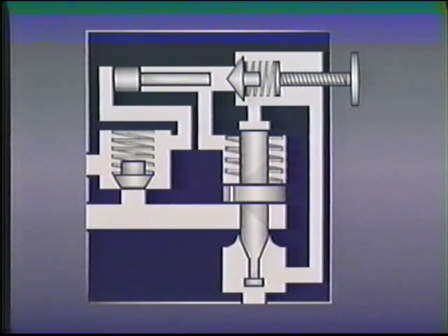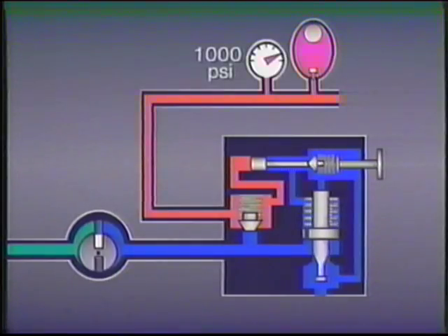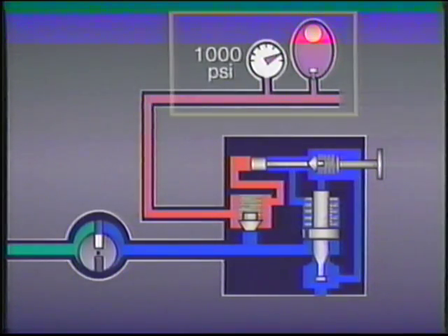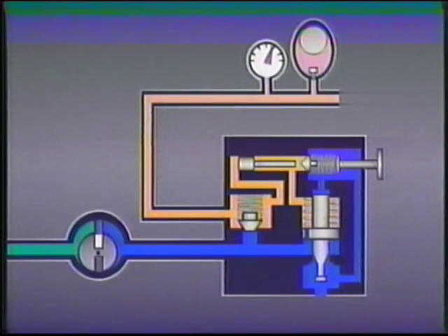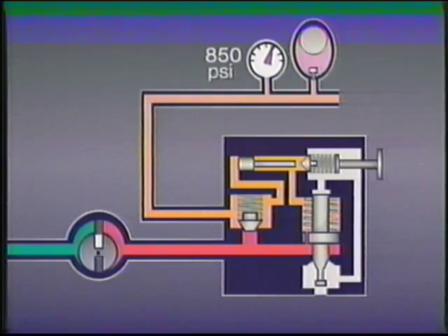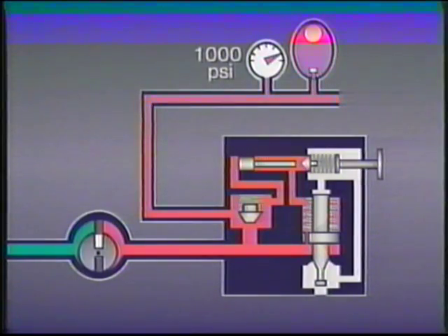This valve, specifically designed for use with accumulators, will automatically divert flow to the accumulator whenever it requires charging, but will unload the pump to tank after the accumulator is charged. In this system, for example, the valve opens and unloads to tank when the accumulator is fully charged at 1000 psi. As the energy in the accumulator is used up, pressure upstream of the check valve drops. When pressure drops to 850 psi, the valve closes and flow from the pump fills the accumulator again.